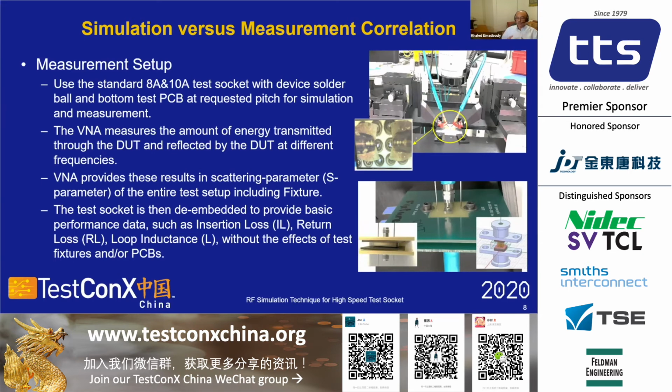Yeah, so usually we ask the customer what the first layer, the high-speed layer, what material is being used. We have a database for Rogers and for Panasonic or any material of the PCB. Or if we don't have this information up front, we'll use FR4, and later on we'll fine-tune the simulation result based on the actual material.